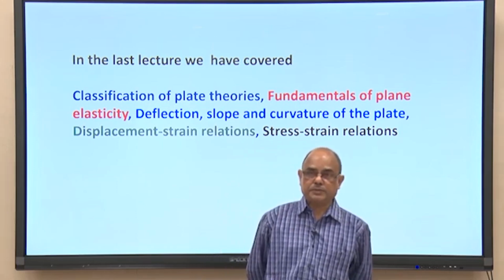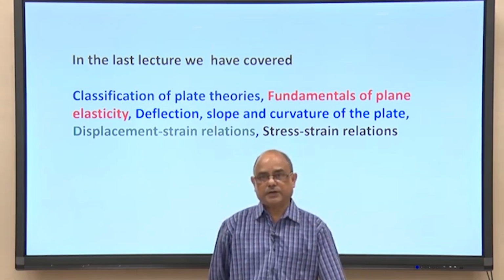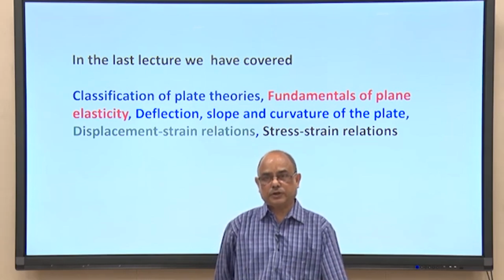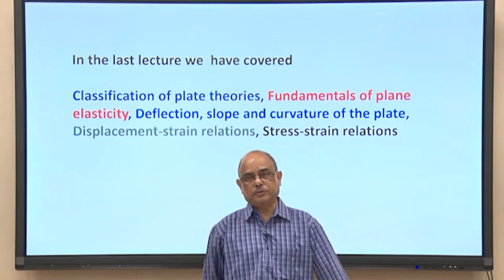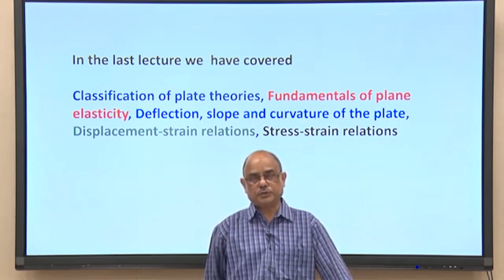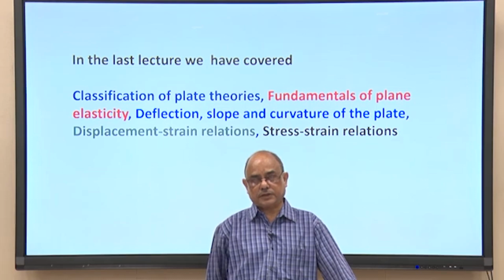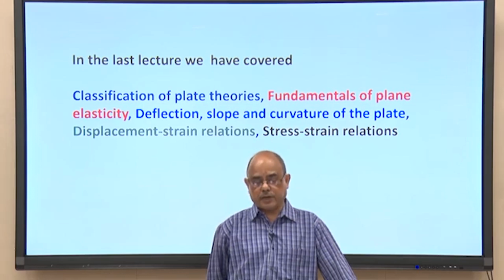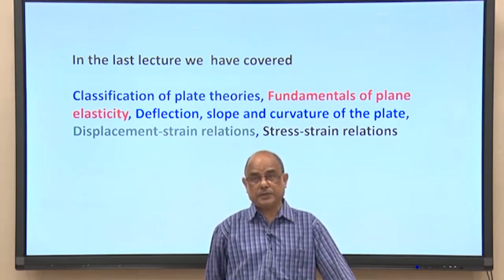Classification of plate theories: you have seen that we have classified the plate into 3 categories: thin plate with small deflection, and thin plate with large deflection, where nonlinearity is produced due to large deflection and geometric nonlinearity. As a result, membrane stress is significant. Then we discussed the thick plate theory.